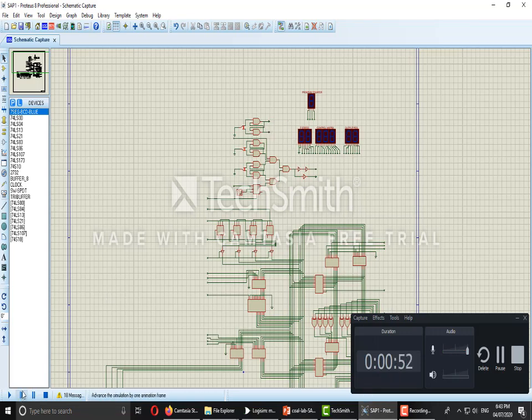So by clicking here, at the first T state the program counter has a value of 0. At the second T state, the program counter value is incremented. You can also see the changes in the control matrix. We only have the display connected to the output register, so you would see only the word at the output, which is from the accumulator, once the out instruction is executed.